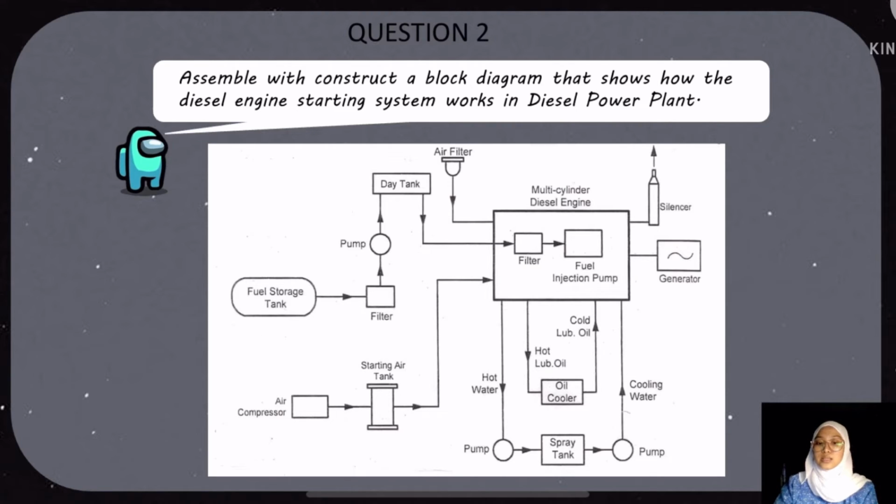In the engine, the air entering the cylinder must be compressed. Fuel must be injected by the end of the compression stroke. After the burning of the fuel, the burnt gas expands and applies pressure on the piston. The shaft of the engine is directly attached to the generator. After the completion of the combustion, the burnt gases are ejected into the atmosphere.